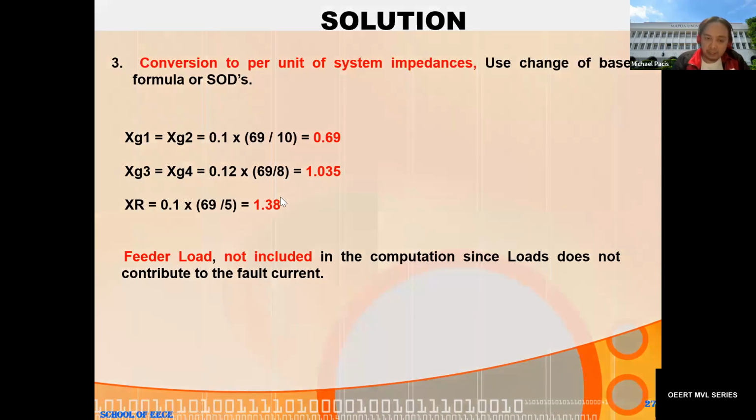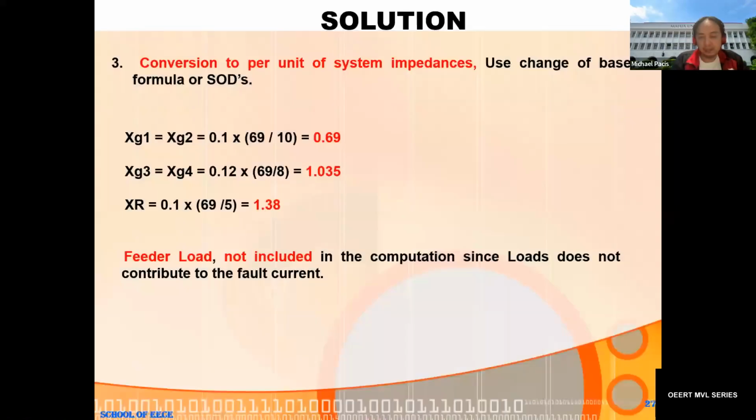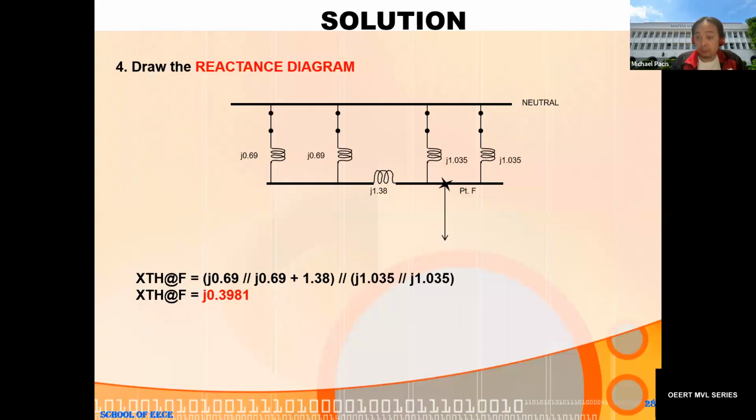The feeder load, you do not need to compute for the percentage reactance simply because it will not be connected to the power system. Okay, you have these values here. Then we will now draw the reactance diagram.